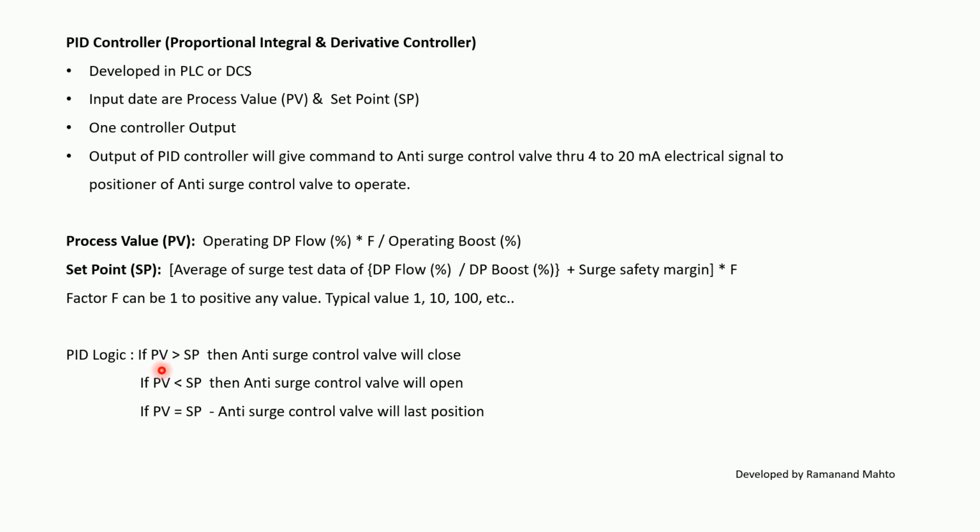PID logic is: if PV is greater than SP, the anti-surge control valve will close. If PV is less than SP, the anti-surge control valve will open. If PV is equal to SP, the anti-surge control valve will stay in the last position.